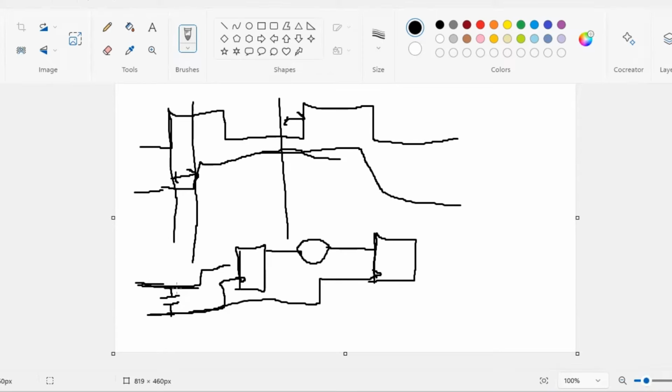This net can introduce delay on this net, early delay or late delay. Early means the clock will come early, fast. If both this one and this one are switching in the same direction, what will happen? This net will be fast and the clock will come fast.